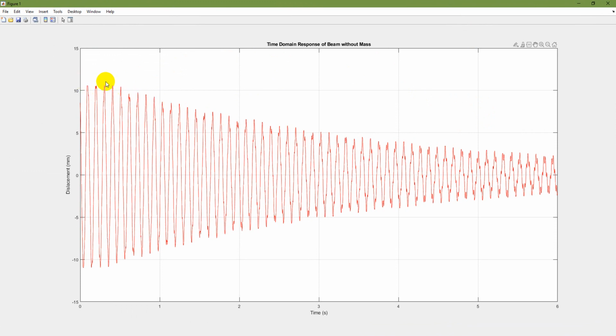Here you can see that first a periodic load is applied until about half a second, and then that periodic force is removed, as is usually done to excite vibration, and then it starts vibrating. Because of air damping, the amplitude of vibration keeps decreasing. The total time to record this signal is 6 seconds. So that is the time domain representation of this signal.